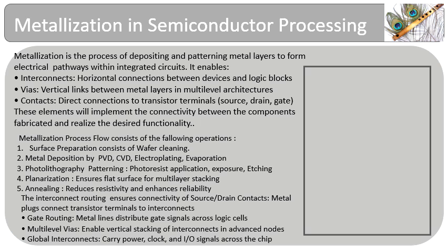The metallization process consists of several processing steps like surface preparation, contact and via cut creation, photolithography, isolation layer and metal deposition, planarization, passivation layer deposition, etc. Some of the processing steps in metallization are shown in the figure.